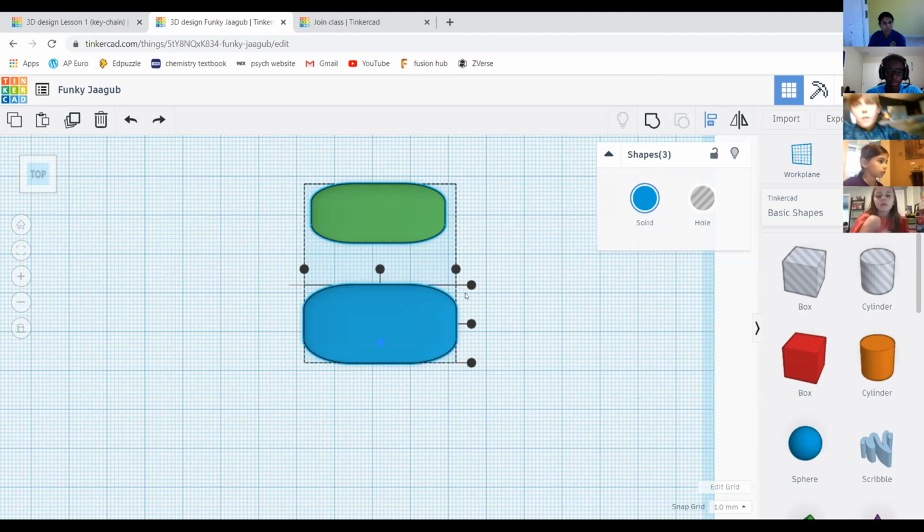All right, have you guys done that? Wait, where's the line again? So Align is at the top right. It's this one with the little bars with one shorter than the other. You can also press L. It's a keyboard shortcut. So remember, click Align, and then you're gonna click on the bigger rectangle.